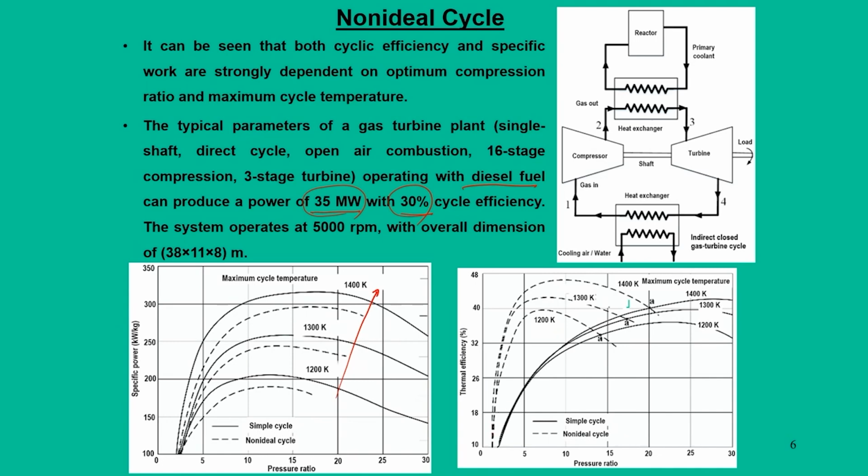So, we can keep on increasing the turbine inlet temperature, but again there is a limitation in terms of fuel, and also a limitation in terms of the materials for the turbine blade. With those restrictions, the upper limit normally doesn't go beyond 1500 Kelvin. The analysis was normally done at three temperatures, typically 1200 to 1400, and we plot them. Once that temperature is fixed, the corresponding numbers also get fixed. For example, the maximum specific power gets fixed.